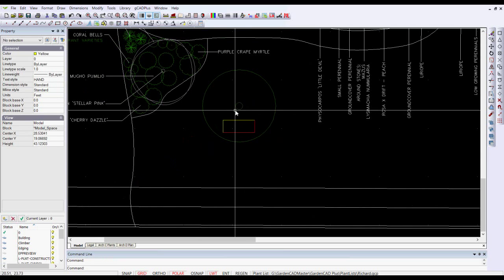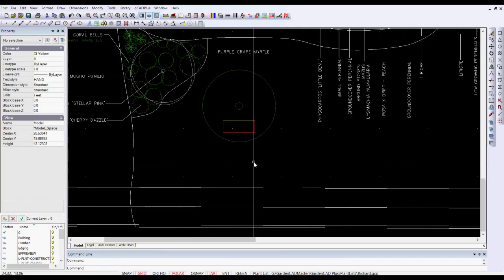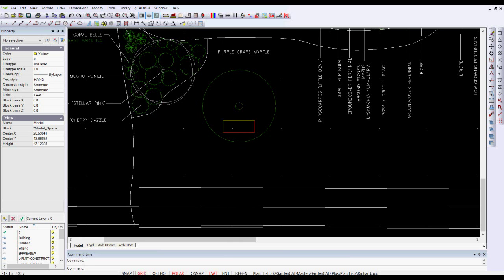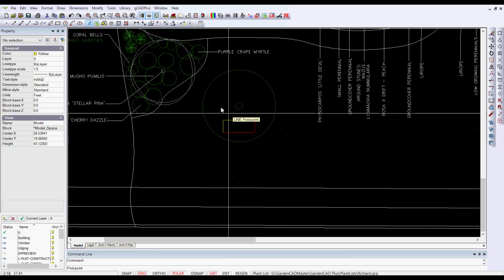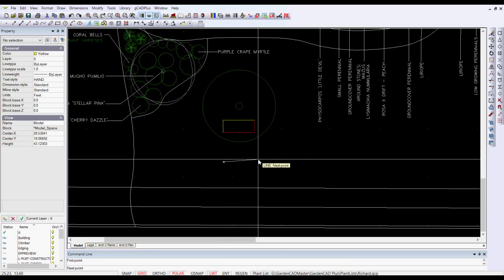So can you see you can draw lines using these different coordinate systems. You need to understand the difference between absolute and relative, and between polar and other entity systems. So let's draw another line, and I'll start much the same way as I did before. I want to head off in this direction.